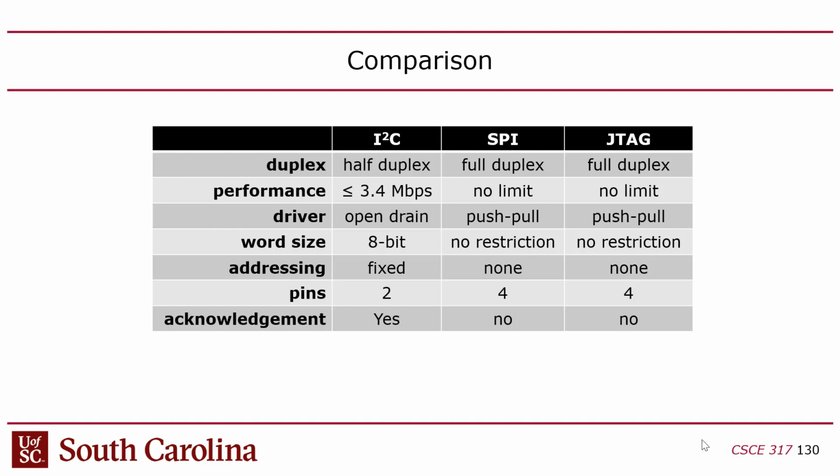What we're looking for with the demo is we're just going to want to see your code, maybe briefly describe how you did it. I mentioned in the lab sheet that there are multiple ways to do it. Specifically, there's the performance counter, and then there was the usleep, the sleep function. So the difference there is that the performance counter is a kind of a clock that runs independent of the CPU, which you can read, and you can measure the amount of time that's elapsed.